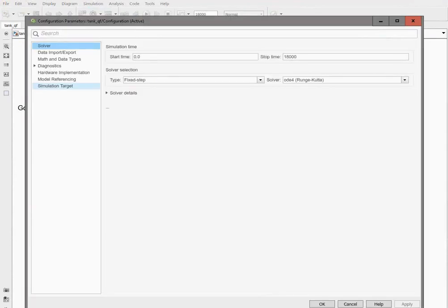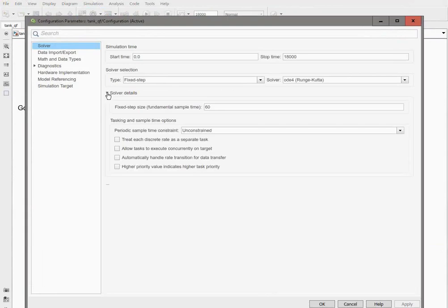Remember, one cycle models 2 minutes of the real-life process, so in solver parameters we specify the time step of 120 seconds, and the final time will be 1 day.